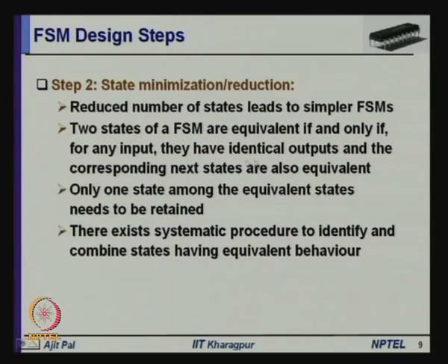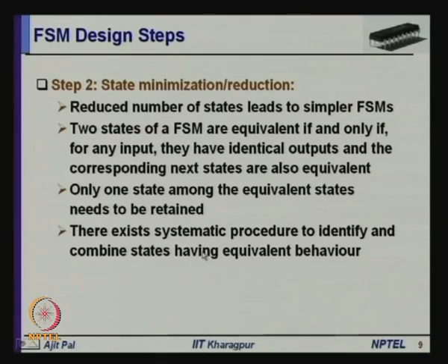So, what you have to do is identify the set of equivalent states, and then only one of the equivalent states will be present in the final state transition diagram. So, it is an important minimization step, and there is a systematic procedure to identify and combine states having equivalent behavior.